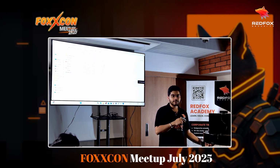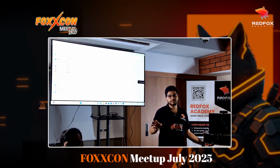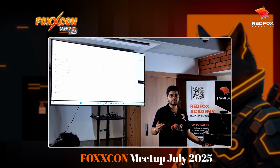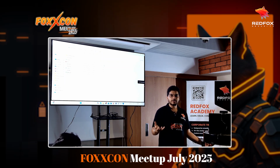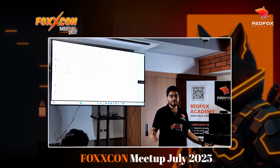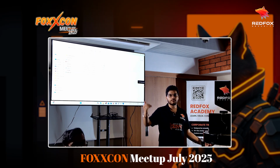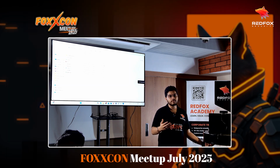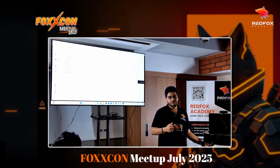Now, since we don't have that here, we need to brute force it, or figure it out. It is not very difficult. There are two or three variations that you generally try. One is 9600, another is 115200, which is one lakh something, and that is a default rate of transfer. Once you hit that, you'll be able to see the data clearly. Even in Arduino IDE, you'll have lots of options for default speeds. I just choose one of those and see if the data is being decoded, and it probably will be, because most vendors use generic speeds.